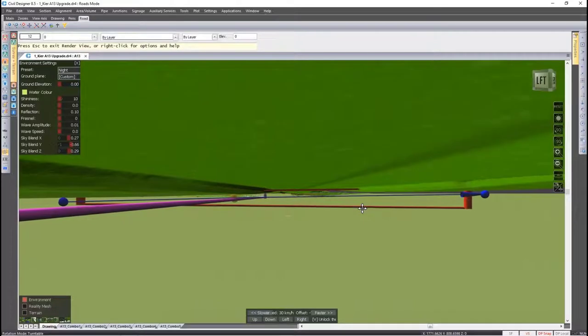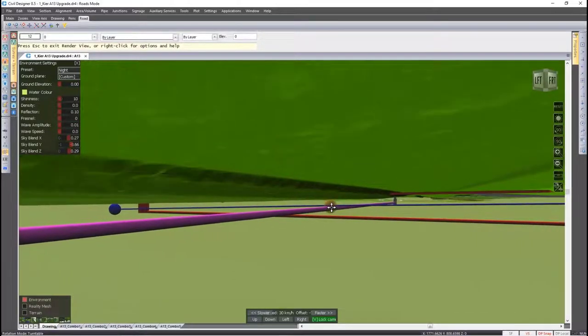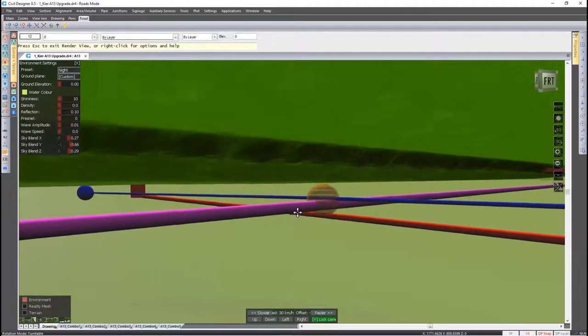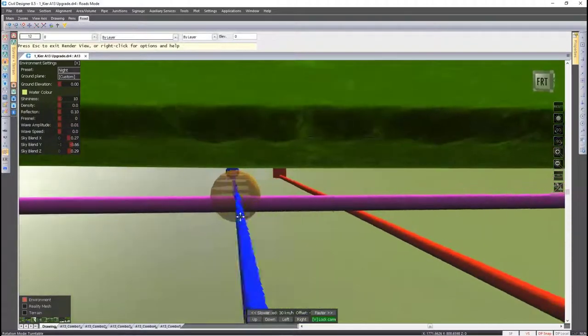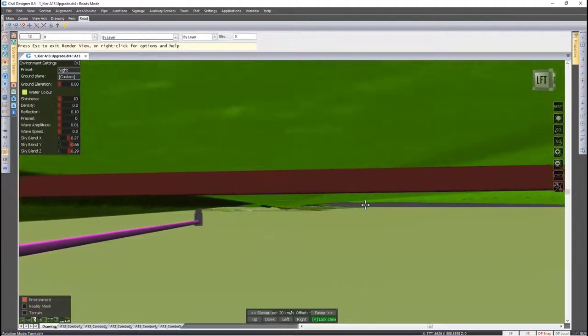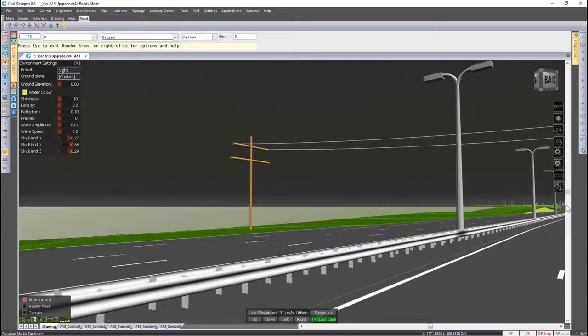And while I'm busy moving, I'm going to press the letter V on my keyboard. If I move my cursor, you can see there's a yellow balloon, and that yellow balloon indicates that we've got clashes between our services. In front of us, this is where we inserted the auxiliary services with the automatic head walls, and this can be viewed from any perspective.